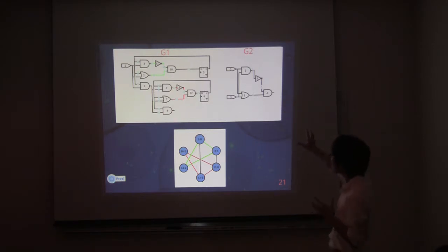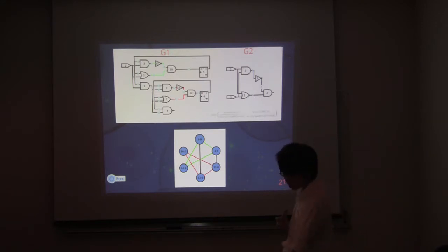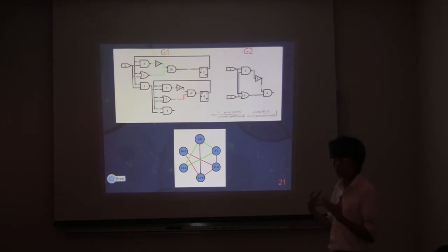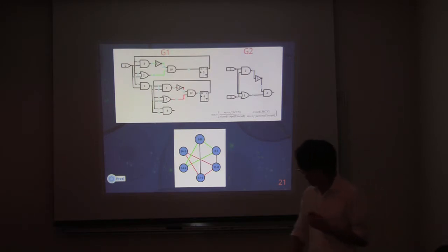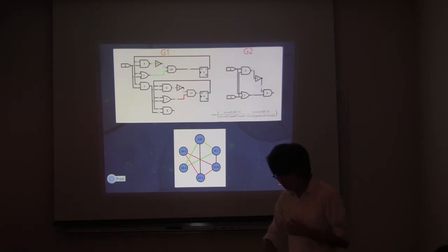However, if the subgraph that is common with both is not the pattern graph, then a similarity metric is also determined to see how similar the two circuits are. Basically, the similarity metric means I want to take the size of the largest common subgraph and compare it with the size of the pattern. If the two sizes are roughly the same, then we know that the subgraph occupies most of the pattern, and we can say that they're fairly similar in structure.